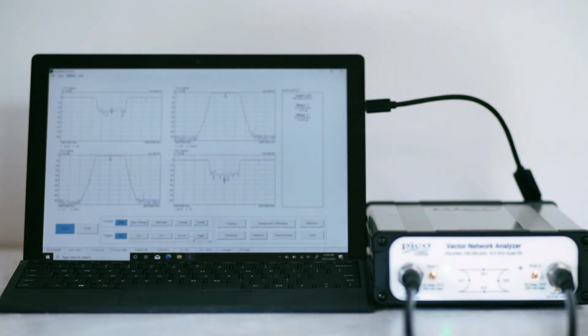They feed a signal into the input and analyze the signal at the output, then go on to characterize the device. They can also feed a signal into the output and read it at the input, which, as we shall see, is an important step in matching impedances for maximum power transfer. Early network analyzers used external signal sources, but now, as in most instrumentation, everything is within a single enclosure.